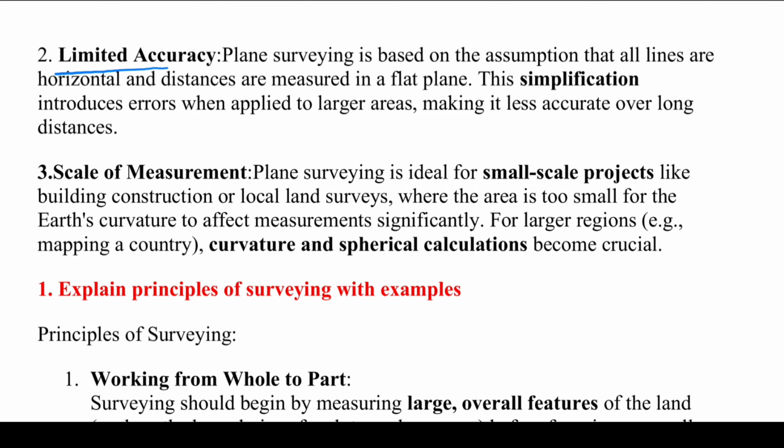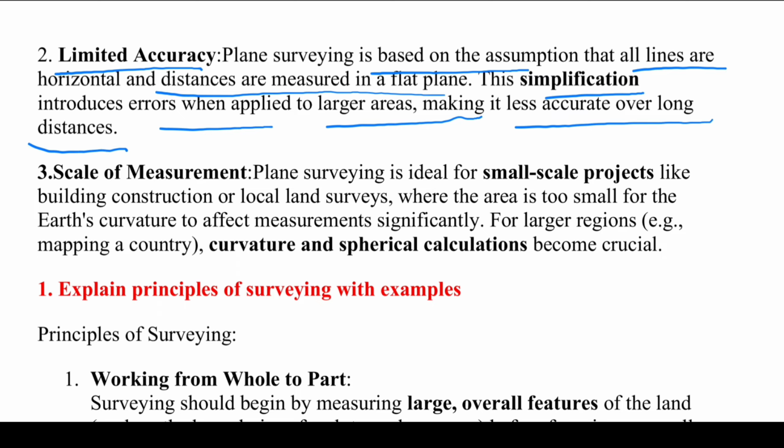Next, limited accuracy. In plane surveying, we assume the surface is flat, and all lines and horizontal distances are measured in the flat plane. This simplification introduces error when applied to a large area, so we get less accuracy in the overall distances.